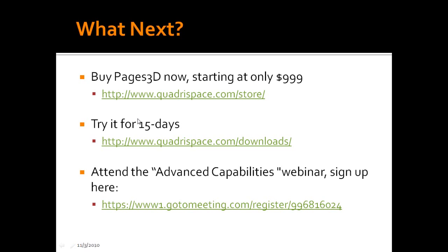On updates. Do you work with the family tables in Pro E? The answer to that in general is yes, but you have to have the accelerator files. This is a question very specific to Pro E users. There's a file called accelerator file that in Pro E, I think it's in properties, you can just turn it on and say, save off accelerator files. And if those are saved off and in the proper directory, when we import, the family tables will be honored based on those accelerator files.